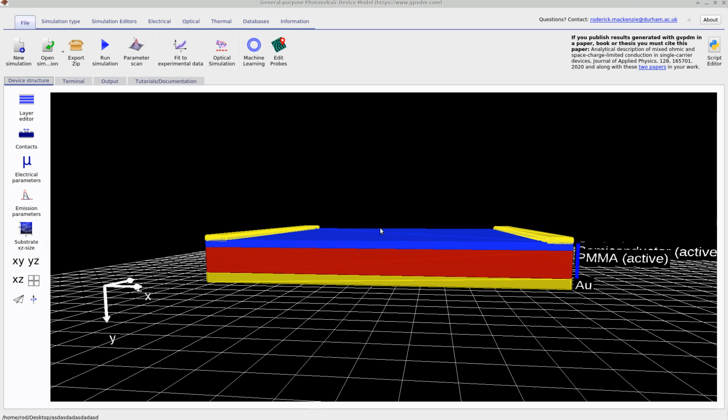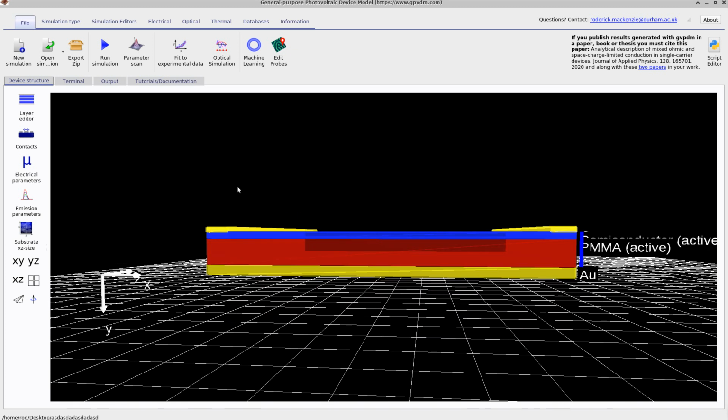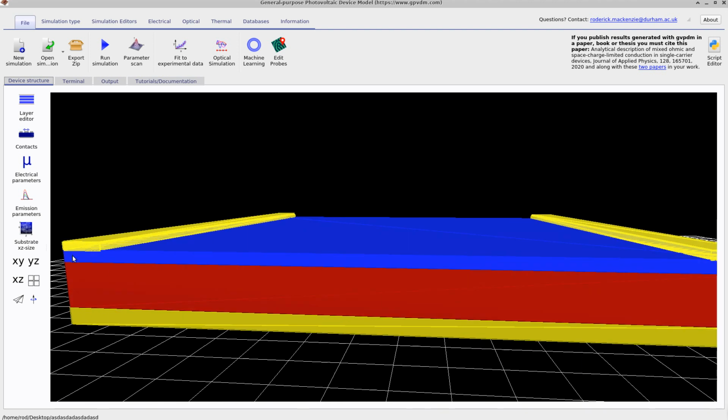So we looked at this device last time, which is a top contact OFET. You've got current coming in at the top. So there's the source, it comes in there, and it'll go along this interface here, or it'll go along here, and come out this contact here, which is the drain. And you control how much current flows along there by changing the gate voltage.